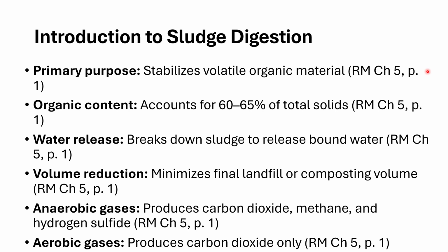And in that primary clarifier, as we mentioned, we're letting gravity do the work for us. The larger settleable or suspended solids are going to come down as we slow down the flow of wastewater, again, from 2 feet per second in the collection system to 1 foot per second in the preliminary treatment and grit washing. Now we're at about 0.05 to 0.03 foot per second.